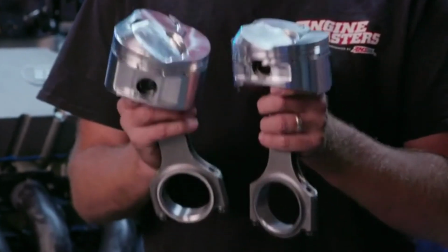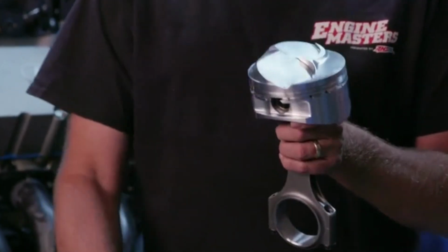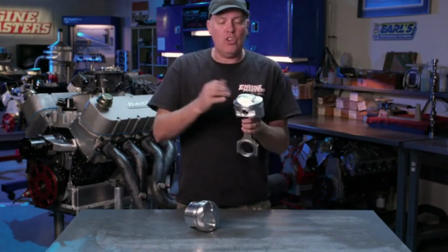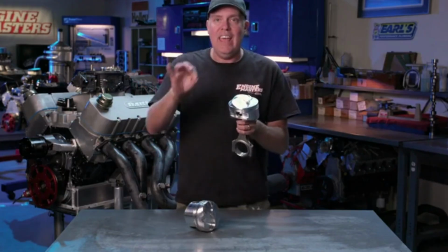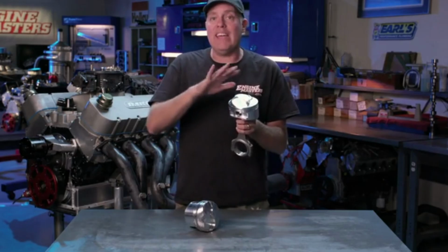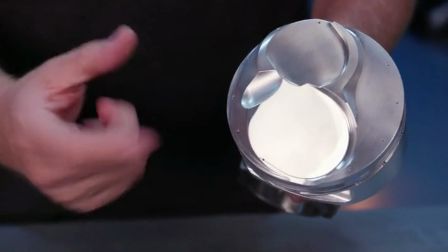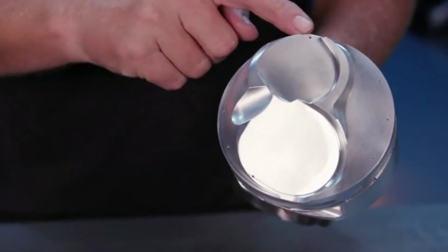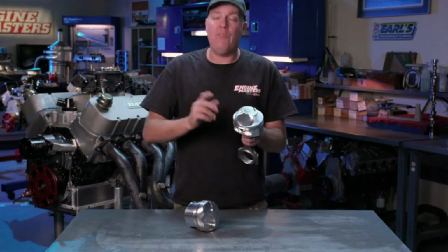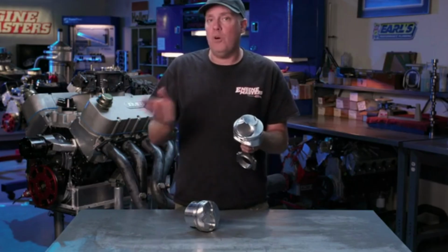These are specific just for this test. What's trick about them is that they are able to go into the Dart cylinder head and collect the data points, basically make a digital map of it, and make a dome that was the largest that it could possibly be for this engine. And they also cut the valve reliefs just for this camshaft. So the final compression ratio is 12.25 to 1.